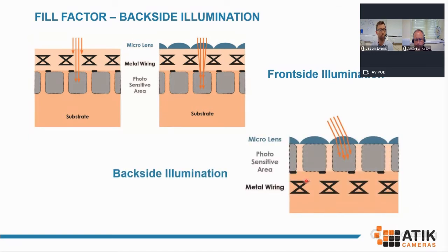And then if we bring up, when it loads up, there we go, the image showing backside illumination. Now, if we look at this, what might quickly become apparent is it almost looks like a flipped over version of the original image we have on the top left. Backside illumination is very much as it sounds. You're using the back side of the sensor and allowing light to pass through there. So this is to help alleviate the impact of components blocking light, and it's a newer technique that has been heavily utilized in recent years for both CCD and CMOS.